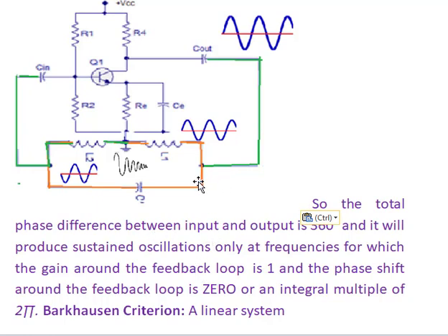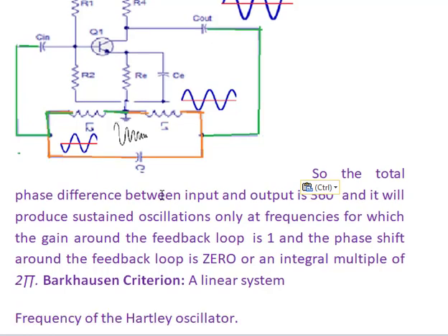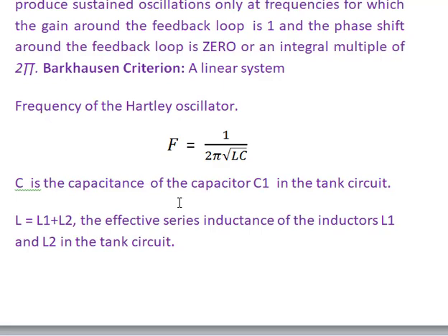The frequency of the output wave is altered by changing the value of C1 or the values of L1 and L2. Generally, the value of the capacitor is changed to get different frequency, constant amplitude output sine waves. The frequency of the oscillator is determined using the formula f = 1/(2π√(LC)) hertz.